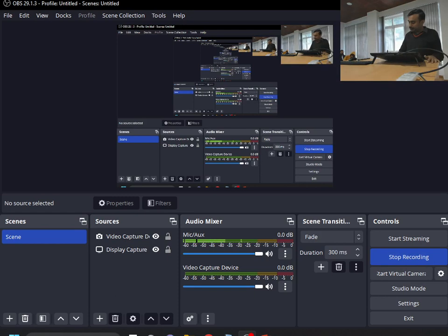Good morning. So this is our 34th session, and in the previous lecture we started the discussion on pressure drop. While we were discussing the pressure drop, two important things we found: if pressure drop is proportional to velocity, then we have laminar flow. If it is proportional to velocity raised to the power 1.75, then we have some other regime which we call turbulent flow,